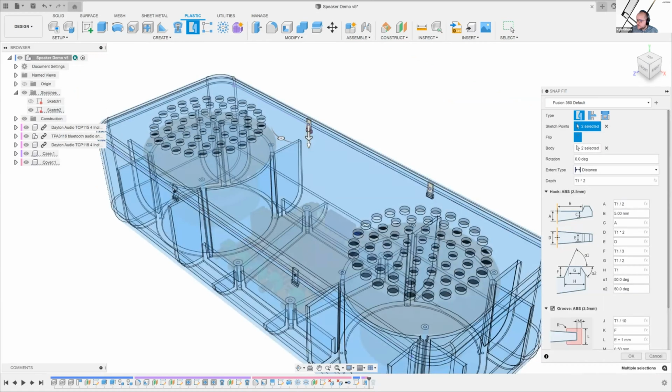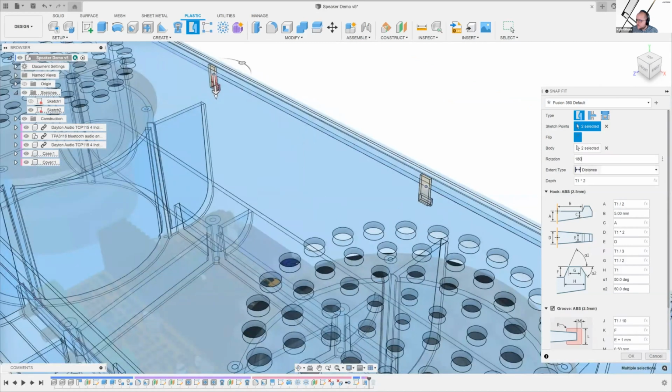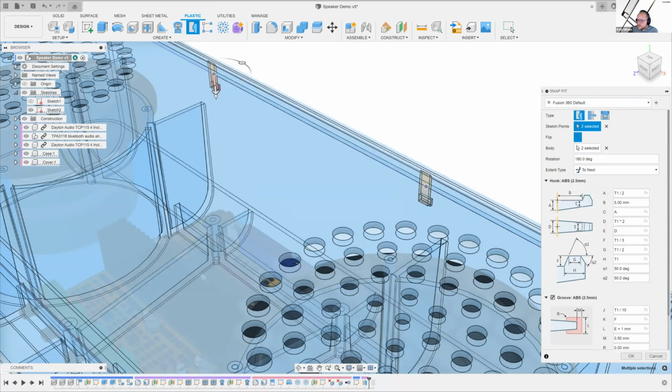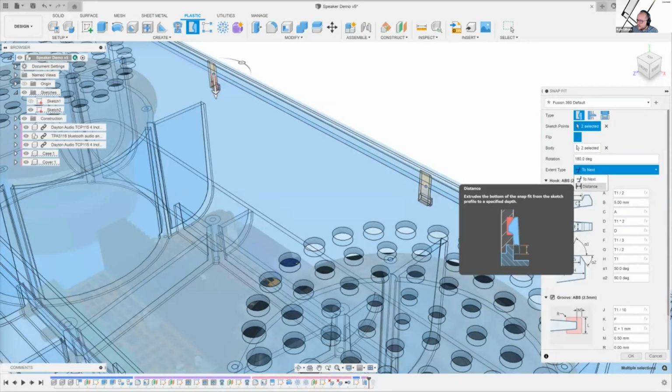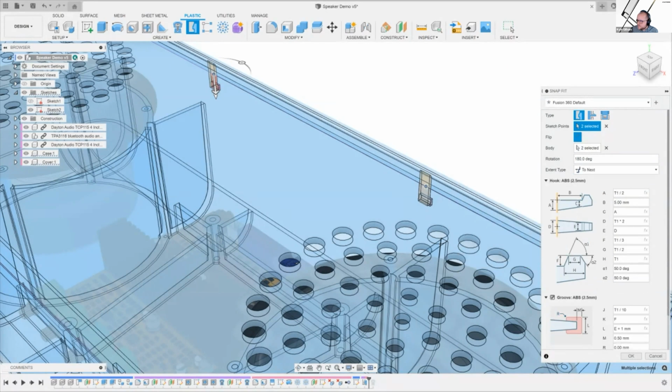All I need is some points there. You can see this is actually rotated incorrectly, so I can rotate it 180 degrees, and there you go. I also want to go ahead and extend these. And you can see I forgot to do it on the last one. The reason we want to do that is because we don't want this undercut here. If we have it only here, right, you would get this undercut here, which is problematic for your tooling. So I'm going to say 2 next.